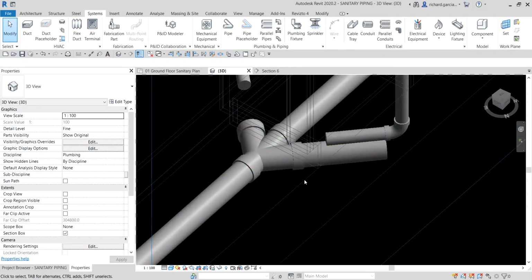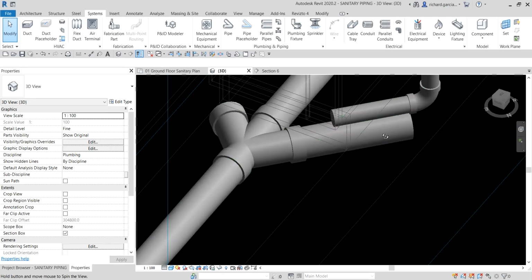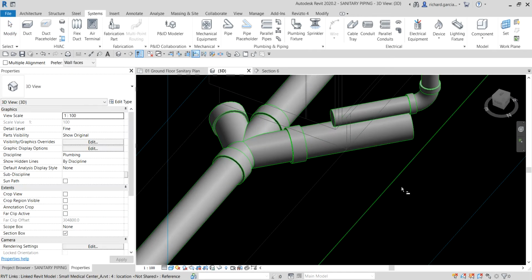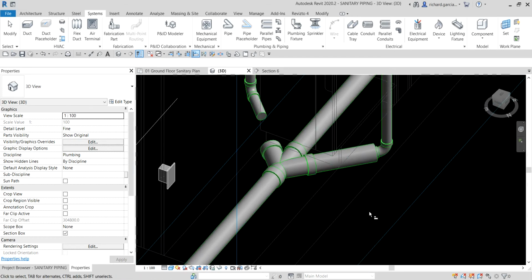After that, I'm just going to align this pipe here. So I use the align tool, hover your pointer, and then you just tab. Make sure it's now selecting the center line, and then click, and then let us now hover our pointer to this pipe, press tab, tab again. There you go. It now highlights the center line, then just click. So they are now aligned properly.